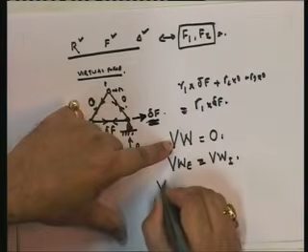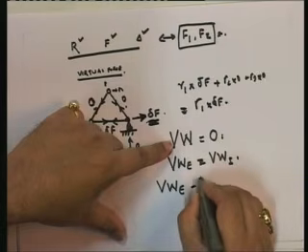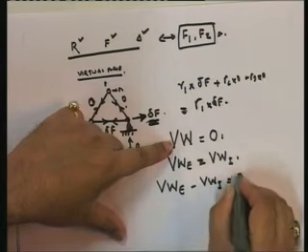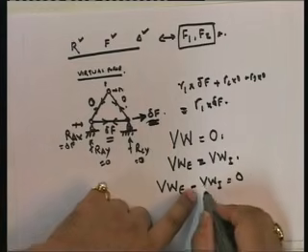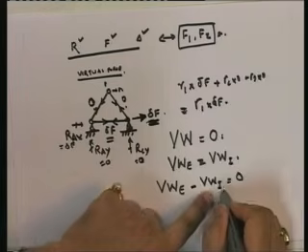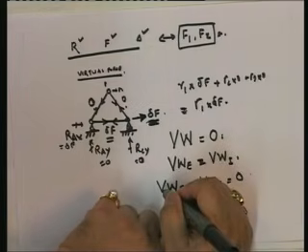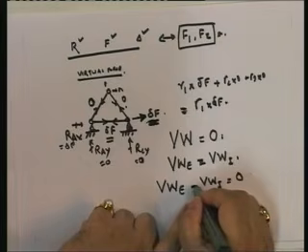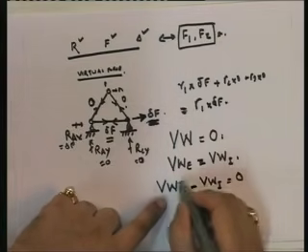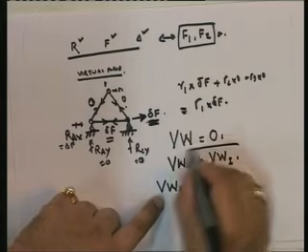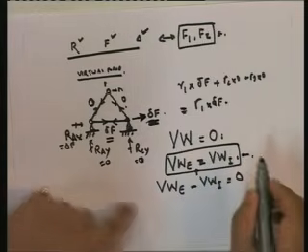So the work done by the internal forces is opposite to that of the external forces. If I separate out the internal and external, this becomes this. Why is this minus? Because all internal forces are reactions, so they oppose the loads. That's why there's always a negative sign. And when I take this, this goes into this. So this is another way of writing the virtual work equation.